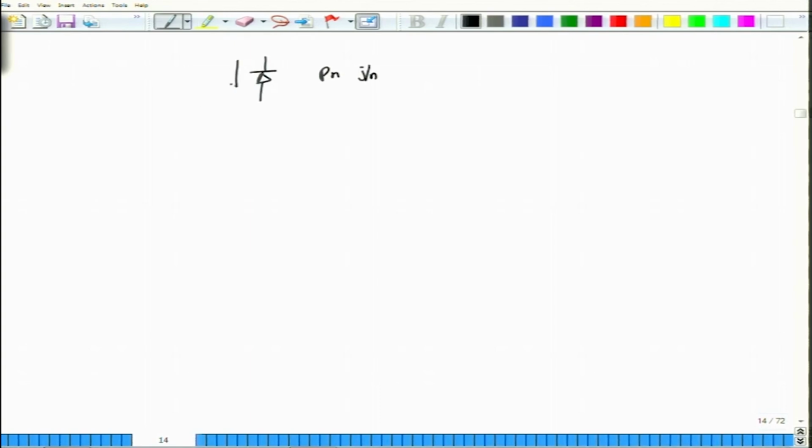When you reverse bias it, there is a reverse saturation current, and this reverse saturation current is no doubt very small, usually in nanoampere, but very good photodetectors pull this noise all the way down to picoampere, and they do this by reducing the surface area, because it can be shown that this reverse saturation current is proportional to the surface area. So if you shrink that, then you can bring down the currents by orders of magnitude, from nanoampere to picoampere.